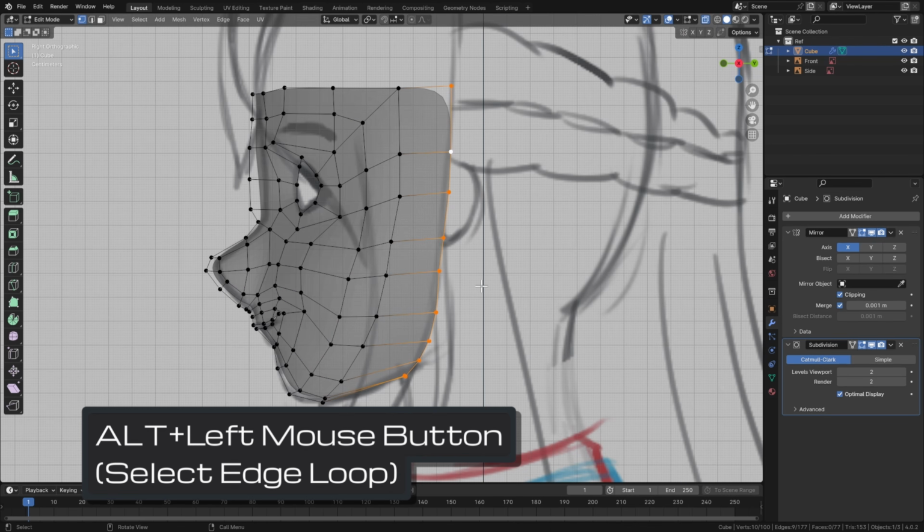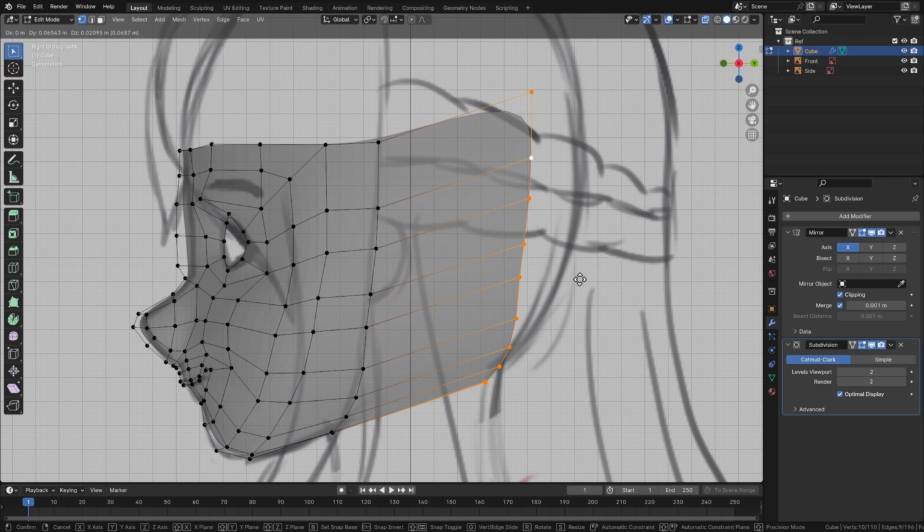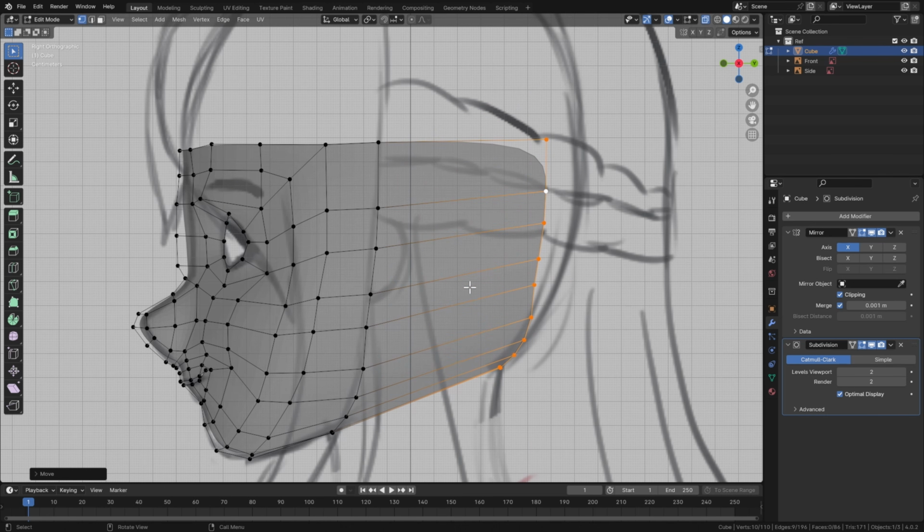Select the edge loop of the back of your face mask and make an extrusion up to the back of the neck on your reference. Scale it down a bit so the top of the head is still roughly flat, and add a loop cut in the middle of the extrusion. The loop cut will help later when we make the body and the ears.